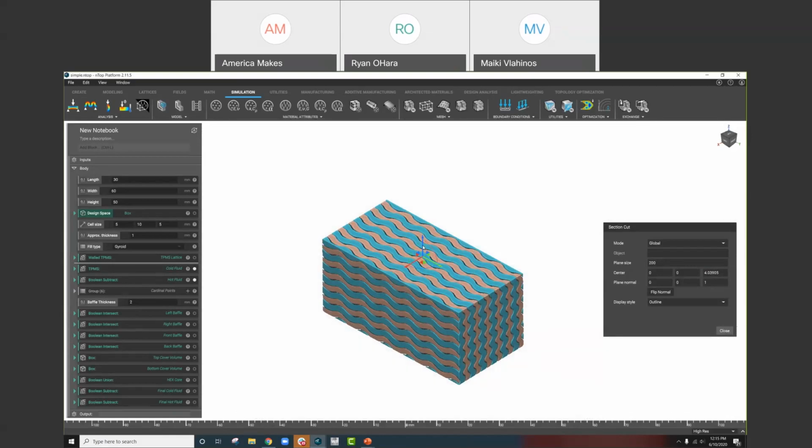And at the same time, you can tell by their shape that they lend themselves to smooth flow topology. But the more distance we travel as a particle of fluid through a heat exchanger, the more pressure drop we're going to experience, and the less efficient the whole structure is going to be.